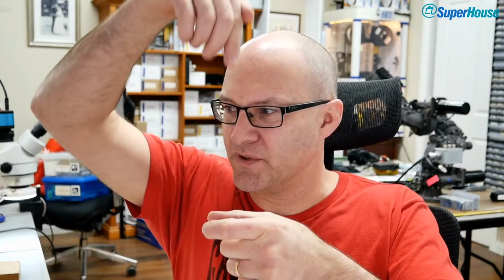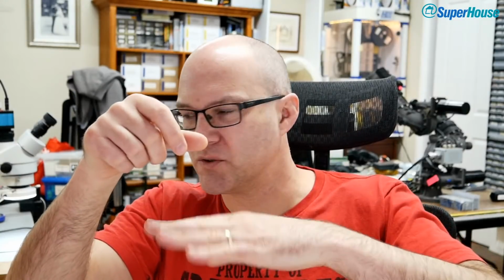So you can put it onto the bed of your CNC machine, move the tip of the tool down until it touches, and you can detect the touch electrically because you have a connection to the tool on the CNC machine, and a connection to the metal plate. It moves the tip down, and as soon as it touches, it gets a short circuit through the tool, and then that's the 0 point for your machine. Well, it's an offset for the 0 point. Anyway, I'm chasing squirrels. Let's not do that.